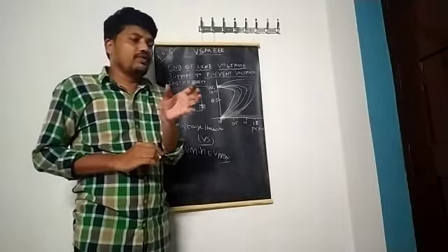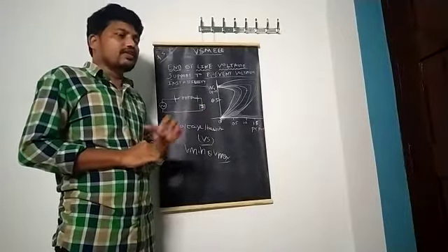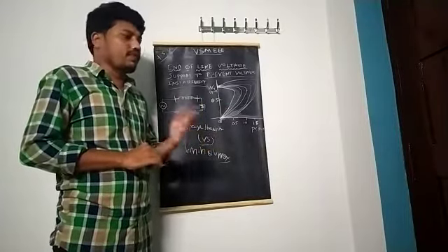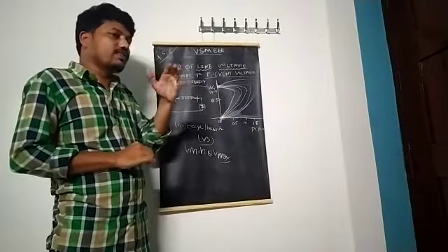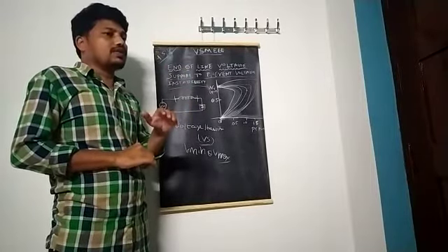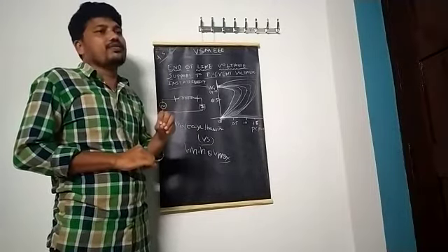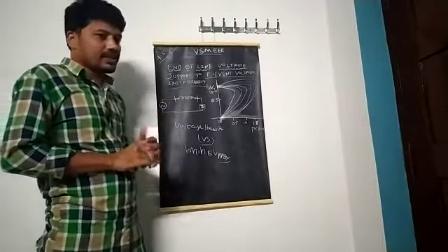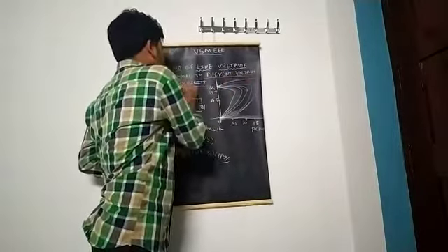If the system is working under normal conditions, it receives some voltage. If a fault occurs, that means an abnormal situation. Any fault, it may be an open circuit fault or a short circuit fault, that is nothing but an abnormal situation. Under that, the voltage may be under voltage or over voltage. So even if a fault occurs, that means in normal and abnormal conditions, the ability of the system to maintain the voltage is nothing but voltage stability. If not maintained like that in normal and abnormal conditions, then we say that it is voltage instability.